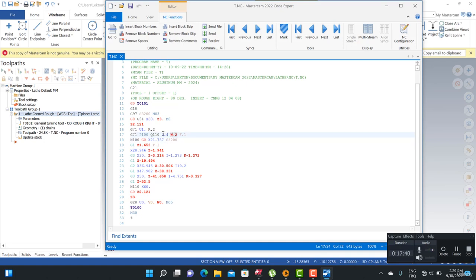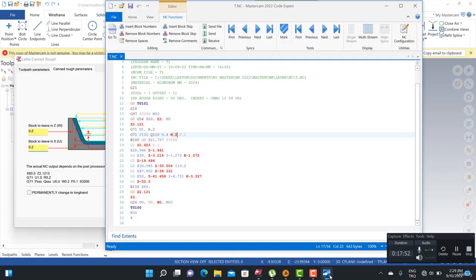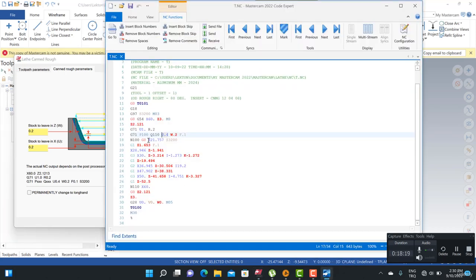When I turn to the parameters options here, you can see that this is 0.2, but when I turn to here, we're going to see 0.4. You know that this is the diameter, but this is half of my diameter. So that's only care about my profile. So 0.2 millimeters here and 0.2 millimeters for that stuff. That's why we can see these kinds of differences in the G71 tool block options. So this is my profile block number, with N100 and 110.